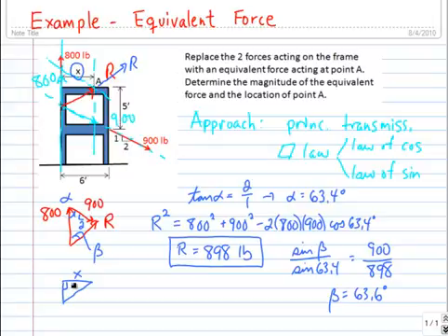We know that the slope of the line of action of the 400-pound force is 1/2, and the width of the frame is 6 feet. So that line of action is going to go up 3 feet to this point. And this is the triangle above that we're looking for. So that side is 2 feet.